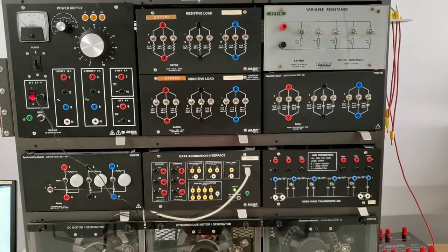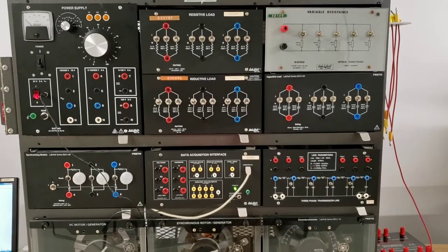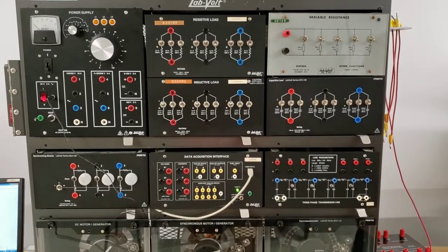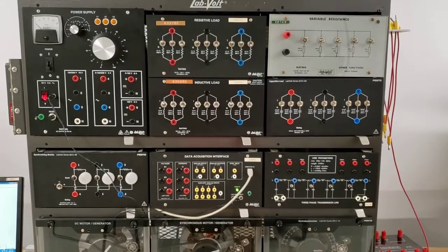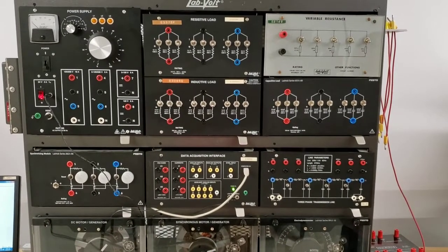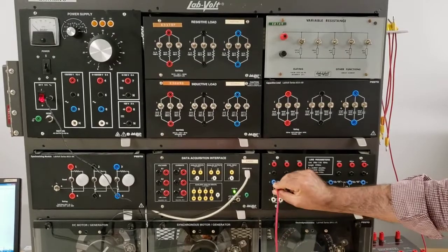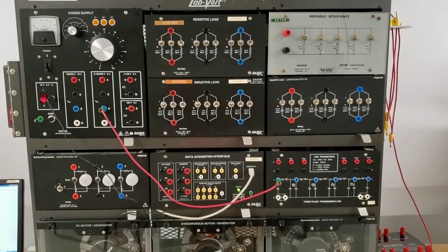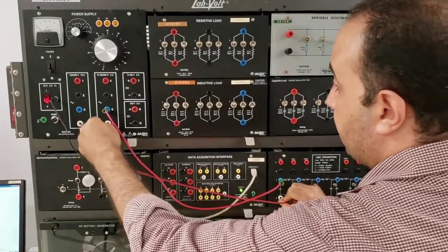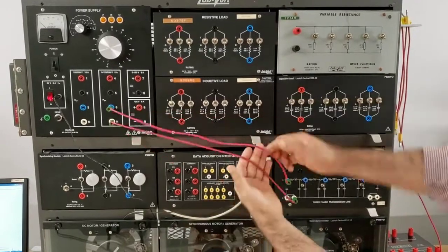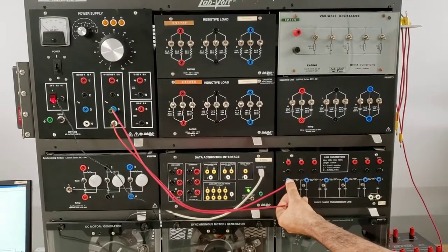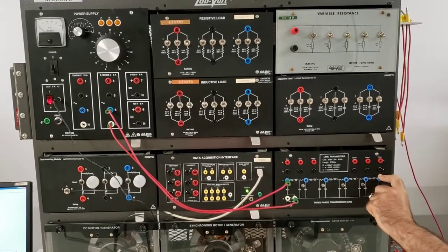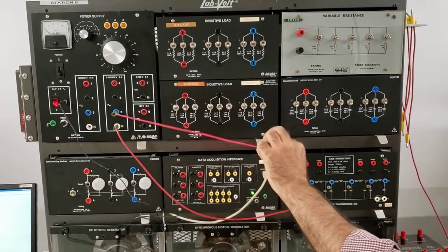So what am I going to do right now? I'm going to connect my model to the power supply. I'm going to use only one single phase because I have a balanced 3-phase system, so it doesn't matter if I'm using single phase or 3-phase. For simplicity, I'm going to use single phase. So I'm going to connect phase C to the power supply, and this neutral is connected to this guy, so the power supply is feeding my sending end voltage. Now, for the receiving end voltage, I would like to leave it open, and I would like to measure its voltage, and I would like to measure the sending end current.